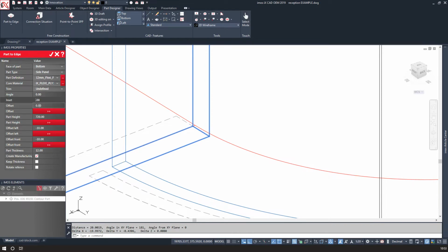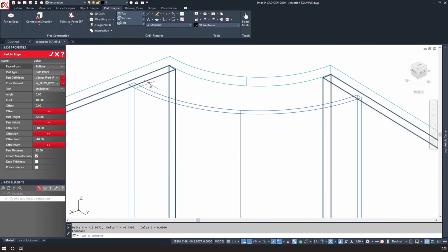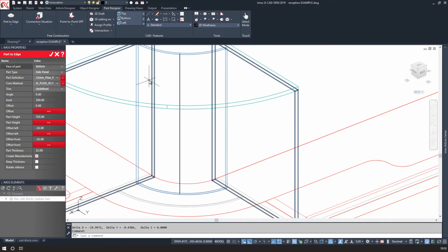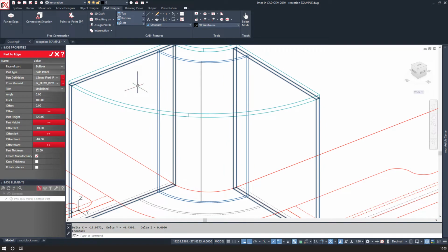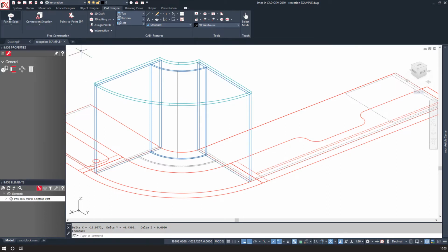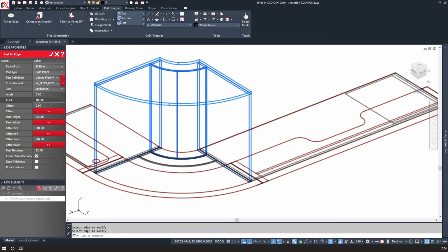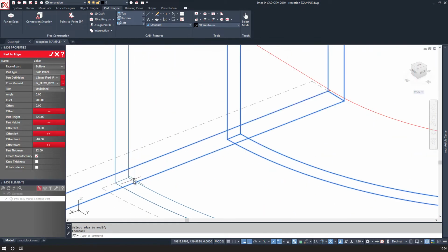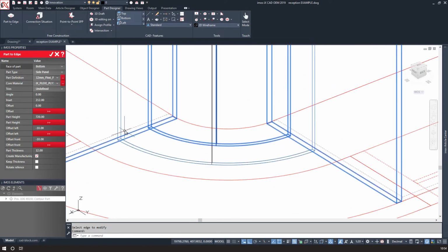This is pretty easy to just take some measurements and tweak this now. So I have my first curved piece of 12mm flexi ply inserted. I'm going to need the second piece as well, so I can have a front and back section as per the drawing. I'll use part to edge again, and again select that rear edge. It will remember my settings, and then I just need to offset that, the additional 112mm. Yeah, I need to push that out a bit further. That's better. Great.